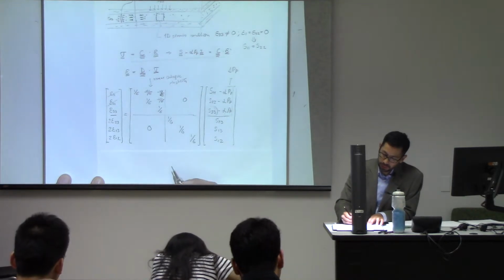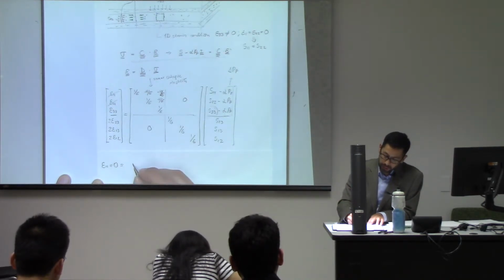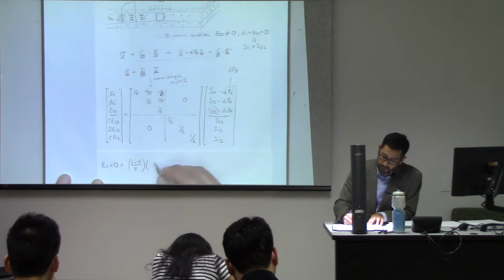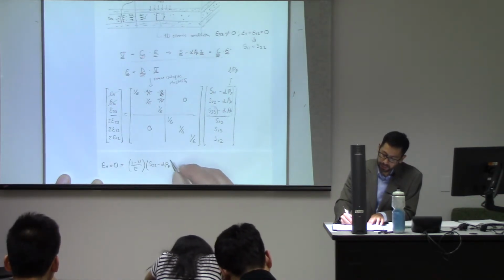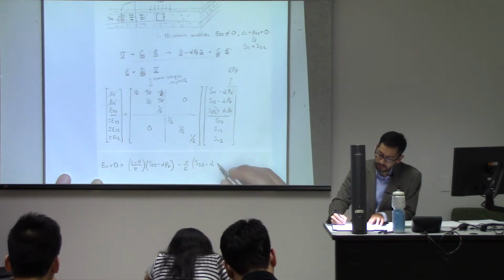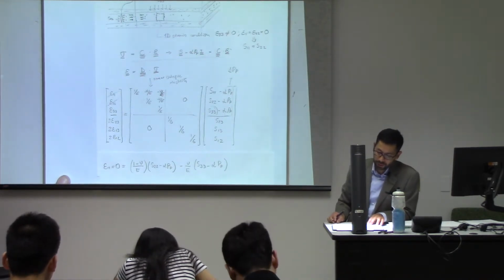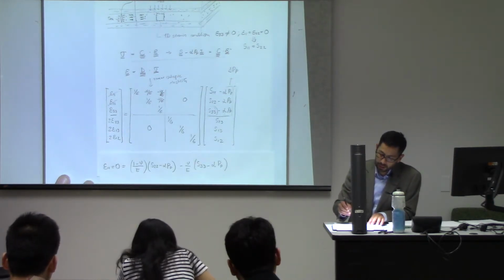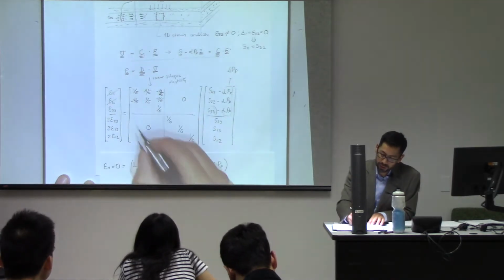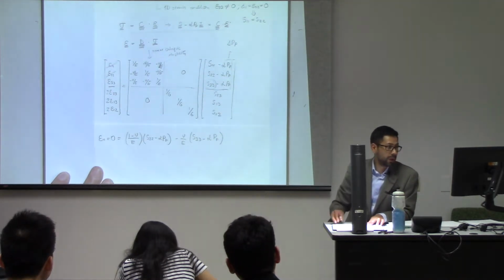Okay, so then I'm going to have epsilon 11, which is equal to 0. First equation is going to be 1 minus Poisson ratio divided by Young modulus times S22 minus alpha pp, minus Poisson ratio divided by Young modulus times S33 minus pore pressure times Biot coefficient, right? And also from here, this equation is going to be exactly the same, right? There is going to be a minus Poisson ratio here. I'm not going to write that because it's the same equation, so I'm just going to go to the third equation.